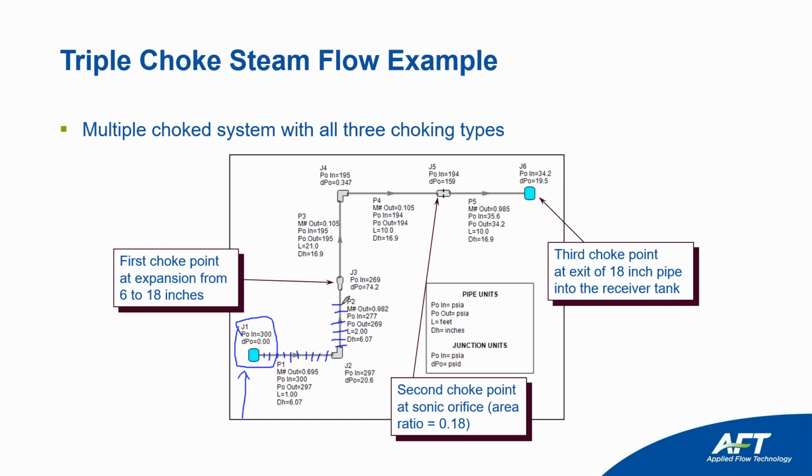If you remember, the Mach number is going to be constantly increasing because your velocity is increasing due to your compressible flow. When that Mach number increases, we get to an expansion here where, look at our Mach number, it's at 0.982. That is where we find out that our gas is accelerated so much up to this expansion point.